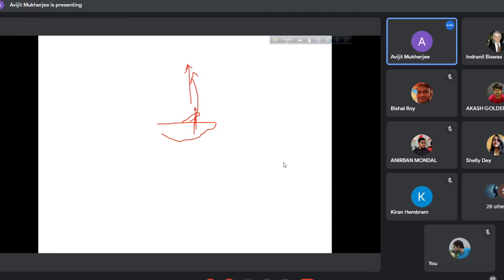But when the plunger is moving down, applying pressure in this way, the valve will be pushed back, so this lid will be closed. But at the same time, if this is the mouth of the gooseneck, another valve will be there. Getting this pressure, this valve will be opened. Something like that, not as simple. That is the one-way valve.